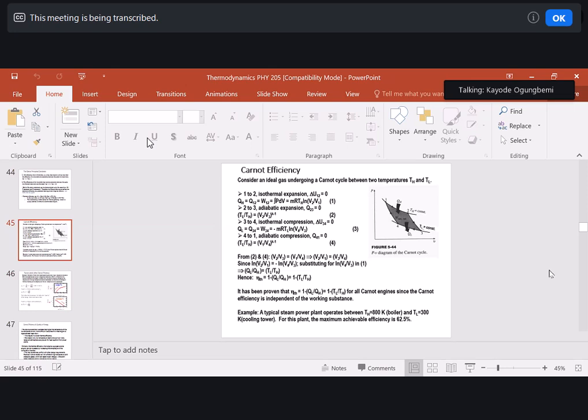Substitute the necessary equation of state there, because you know that PV equals what? nRT. Remember that? Yes, sir. So when you substitute that, what you have is nRT ln of V2 over V1.